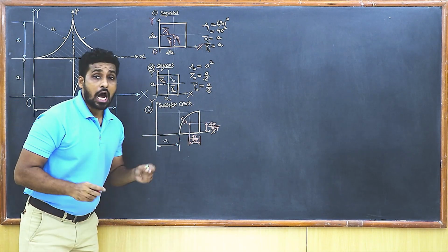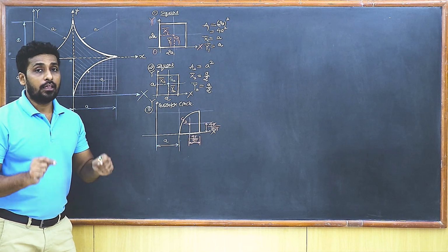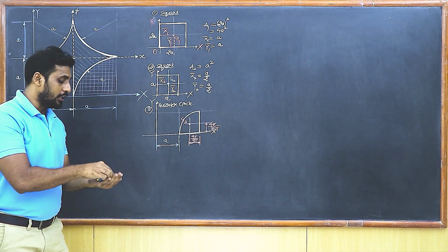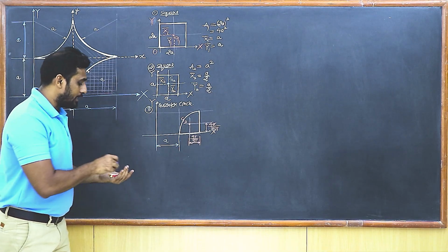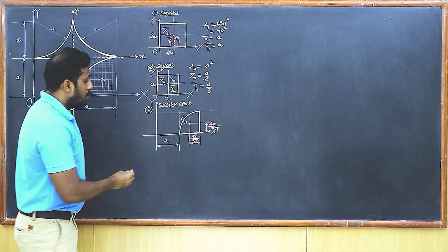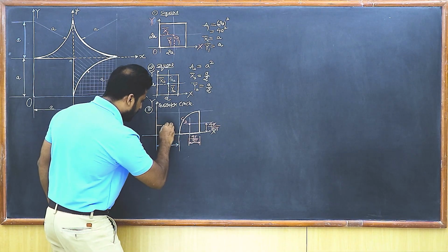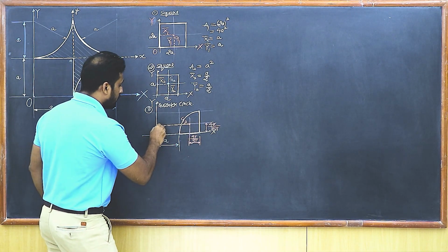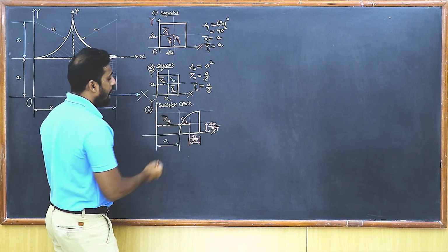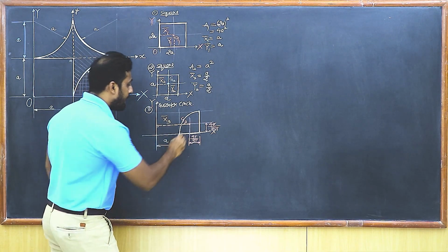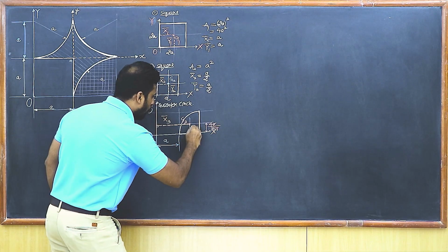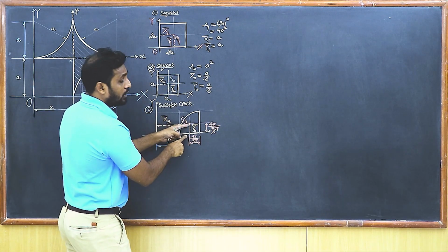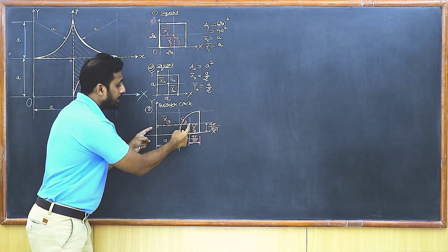This is G3. Now you remember, you want to tell the coordinates of the centroid with respect to the original x and y axis. So the distance from the y axis becomes the x coordinate, isn't it? The distance from the y axis. So this is the distance from the y axis. So this is going to be x3 bar, and the distance from the x-axis is going to be y3 bar, isn't it? So that's x3 bar and that's y3 bar. So observe carefully, look at this x3 bar.